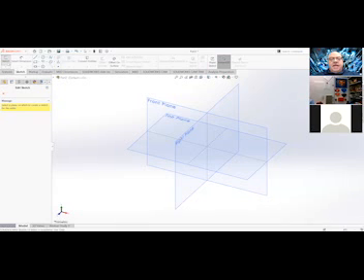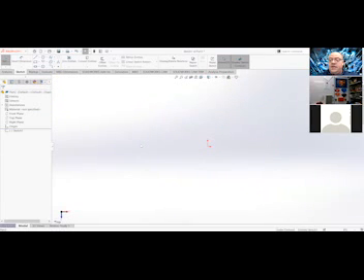Now that you have your sketch active and you're ready to go, we need to choose where we're going to draw. We drew the front of that base, which is actually the top of the bottom. It's kind of a weird thing. So I want you to come put your cursor on the top plane. It's highlighted with a kind of orange outline. We're going to work on the top plane of this. That's going to keep our base oriented in the way it will be with the final assembly. So once you left click on the top plane, it's going to come and face you.